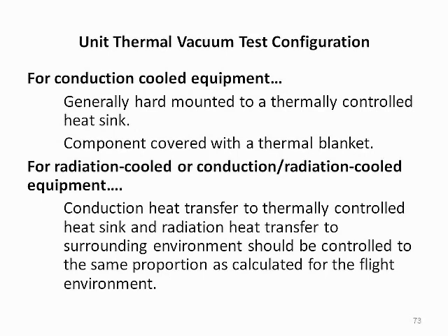Conduction-cooled equipment is generally hard-mounted to a thermally controlled heat sink and the component covered with a multi-layer insulation blanket. Radiation-cooled or conduction and radiation-cooled equipment is typically tested with conduction heat transfer to a thermally controlled heat sink and radiation heat transfer to the surrounding environment. The conductive and radiative portions of the heat transfer should be controlled to the same proportion as calculated for the flight environment.